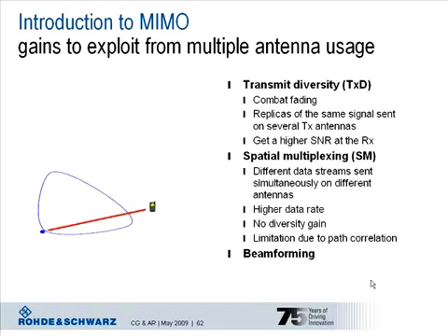Now, not to forget a third possibility of using multiple antennas. In the case of beamforming, an antenna array with closely spaced antenna elements is used to focus the energy in the direction of the terminal, and ideally also to null out interferers. This is achieved by adapting the amplitude and gains of each antenna element to form the beam. Beamforming is also supported in LTE, and it is especially beneficial for TD-LTE, the TDD mode, because of the reciprocity of uplink and downlink channels in TDD operation.